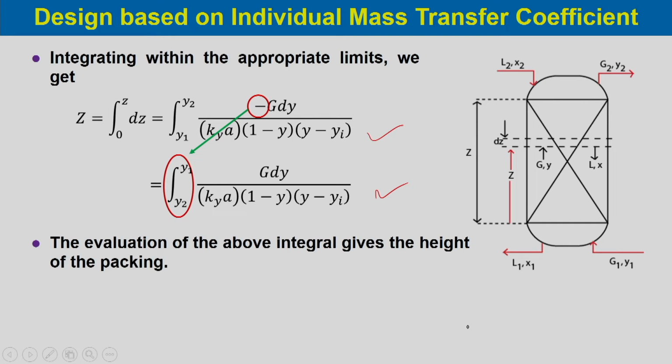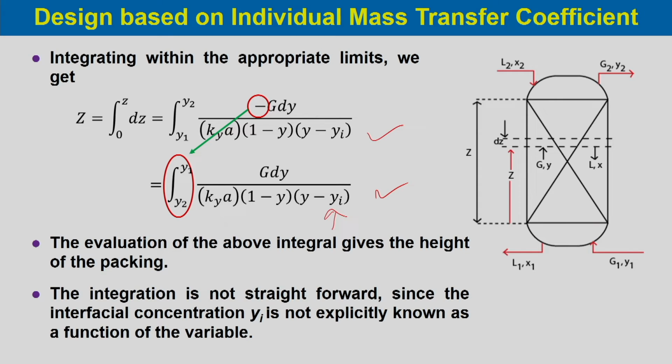The evaluation of the integral given over here for the height of the packing requires the calculation of yi, that is the interfacial concentration. The integration is not straightforward since the interfacial concentration yi is not explicitly known as a function of the variables. Since yi is not known, this integration is not so straightforward. So, we have to find ways to determine the interfacial concentration.